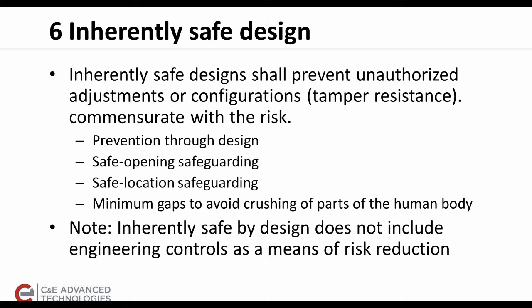A typical example might be where the pressure available on a clamp is limited by design, and someone goes in and changes the pressure reducing valve, and in that way reduces the safety function by increasing the hazard due to pressure injuries, crushing injuries, that sort of thing.